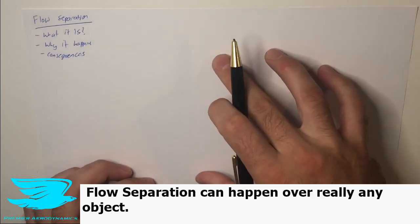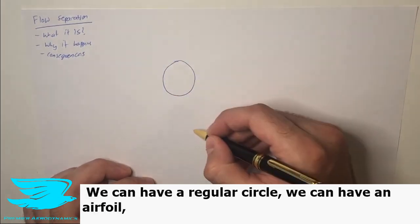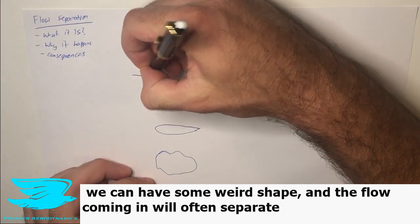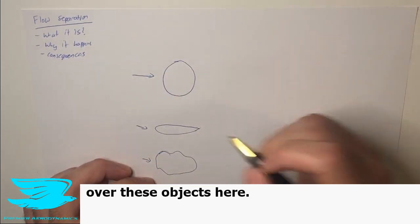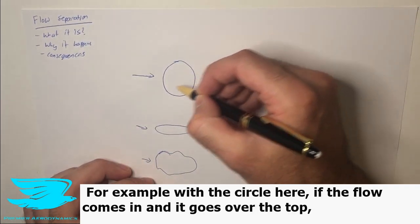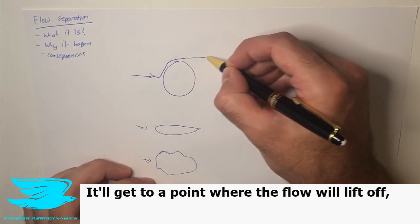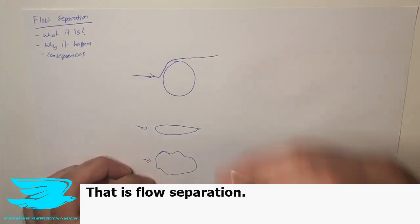So flow separation can happen over really any object. We can have a regular circle, we can have an airfoil, we can have some weird shape, and the flow coming in will often separate over these objects here. So what is it? For example, the circle here: if the flow comes in and then goes over the top, there'll be a point where the flow will lift off and it won't really follow this geometry anymore. That is flow separation.